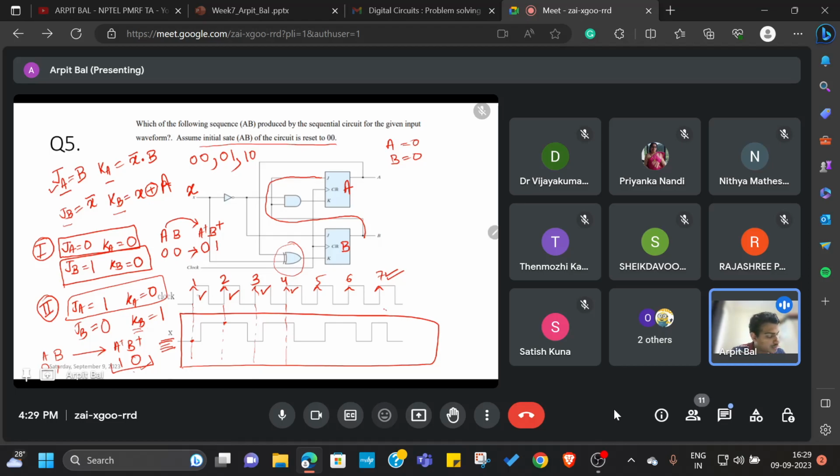You should be able to figure out whether the clock is positive edge triggered or negative edge triggered, because had this been negative edge triggered, then the X value that goes to the input would be 1. But because we figured out it's positive edge triggered, the X value that is sampled by the first clock edge was 0.